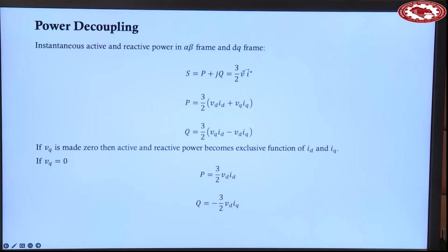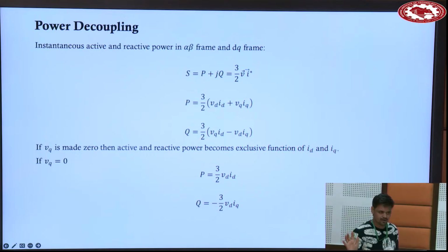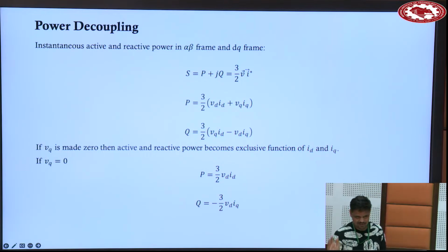In grid connected converters, we align our PLL such that it will give you phase A information. So, depending on your reference frame, you are assuming Q up or down. It is a very flexible system, but you should be very consistent with whatever notations you have taken. If you have taken D here, Q here, go with that, but you should be consistent throughout your work. There is no implication that you need to use only this. You can use anything.